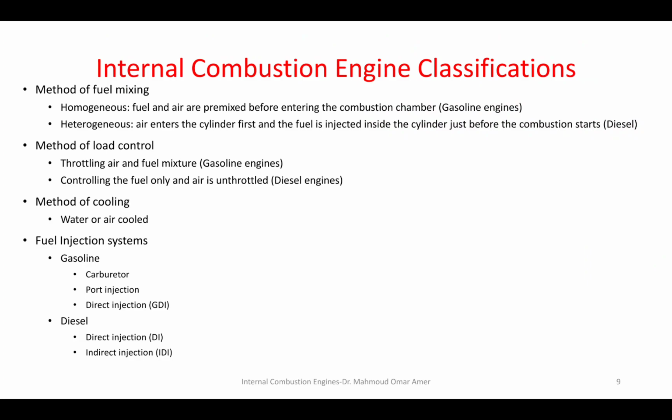Okay? So the entering air from the intake manifold mixes with the gasoline fuel, and when they enter the cylinder, they still mix during the intake stroke, and during the compression stroke they are still mixing until you start the spark at the end of the compression stroke. So when the spark is ignited and the fuel ignites, all the fuel is mixed very well with air. So the combustion is homogeneous and all the fuel burns right away.